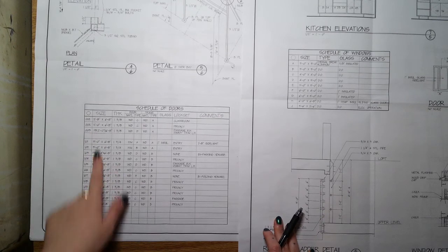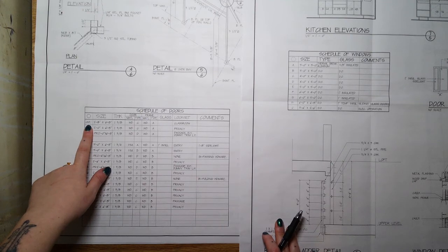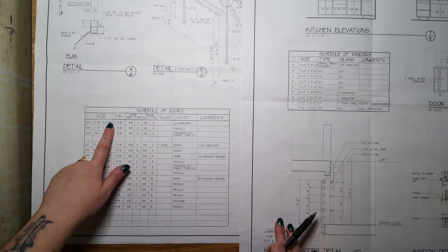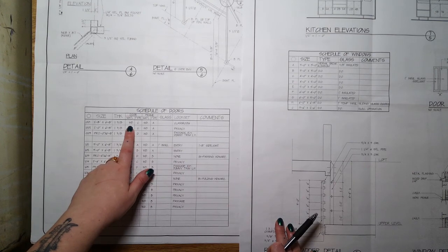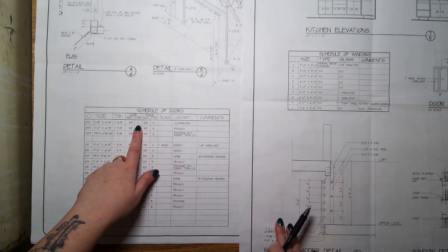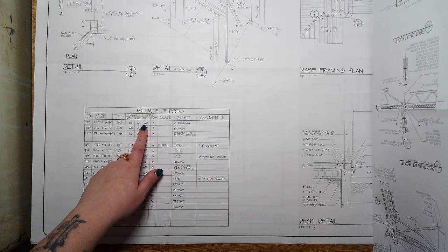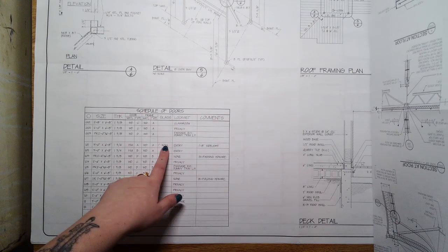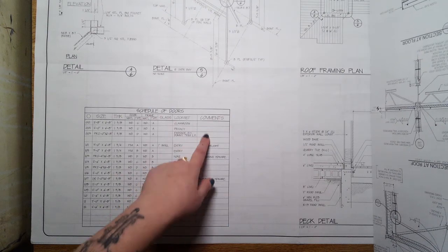But this little table here is telling me that door 001, that's its overall size, so it's 2 foot 8 inches wide, 6 foot 8 inches tall. The door thickness is 1 3/8. It's made out of wood. It's wall type C, which I don't necessarily know exactly what that part means. The frame is also made out of wood, and it's type A. If it has glass on it, it would have it there. And then maybe what type of lock is on there, and any other little comments that might be included.